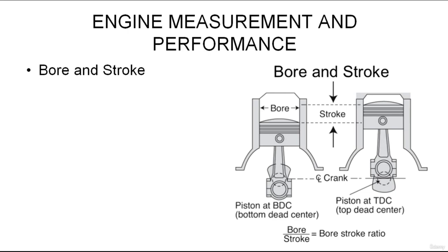Over square engines offer the opportunity to fit larger valves in the combustion chamber and use longer connecting rods, which means over square engines are capable of running at higher engine speeds, but because of the size of the bore, the engines tend to be physically larger than the under square engines. Under square engines have short connecting rods that aid in the production of more power at lower engine speeds.